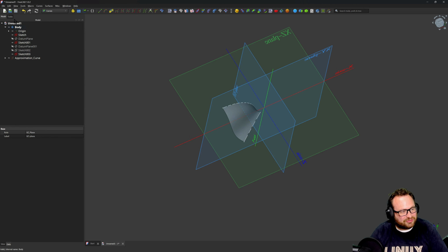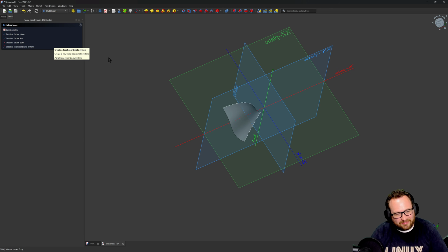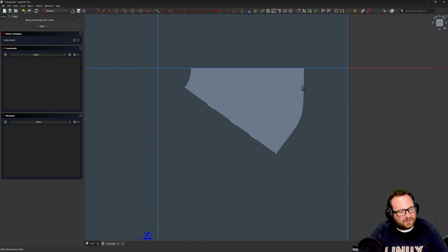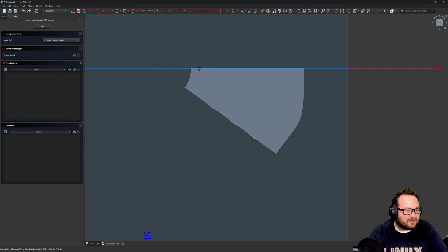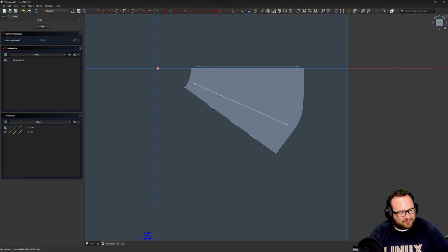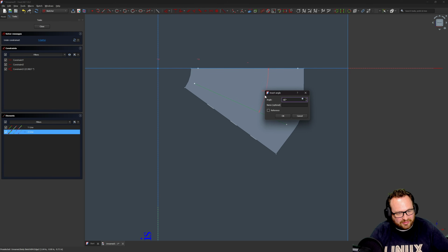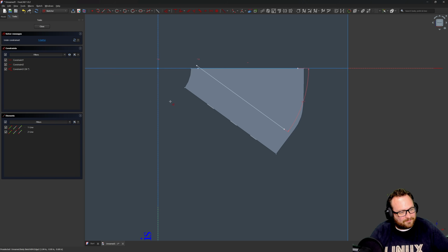I can create a little extrusion. So I'll jump into creating a sketch there. Again, I can use Part Design, right? I'm using a hybrid of Part Design and Part features, which there's no problem doing for now, at least. And we'll create a sketch here, a sketch there. We'll make sure that I'm H for horizontal, and I've got my origin point, and this line will now be horizontal. I'm going to say D for dimension and establish a 36-degree difference there.